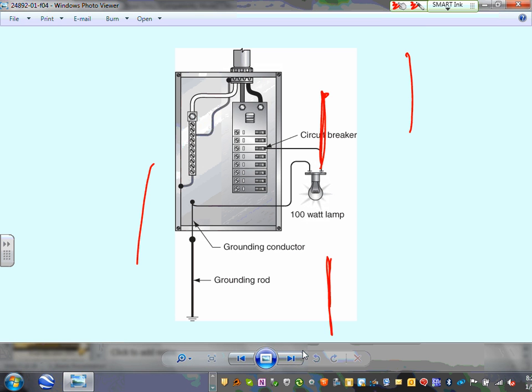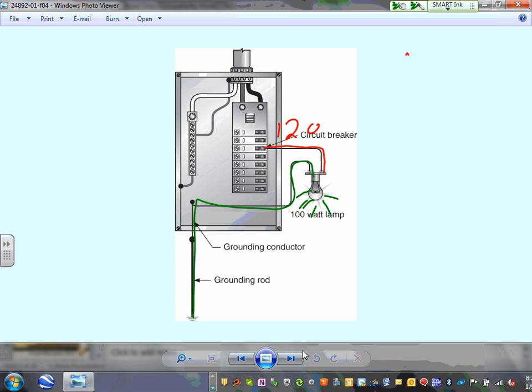Adam, since you're an electrician, you care, and this is how they used to measure the impedance, guys. So they bring a 120 here, and you tie it to this side. From this side, you go directly into the ground rod. And if this goes on, good, this means you have a good grounding system. That's just an indication. It's not really a good, reliable way.